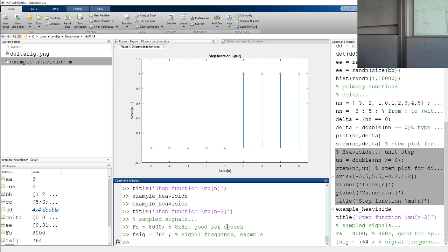So if you are using this capacitive type microphone, you basically can just use the 3 volt bias. Then this voltage should be around that one. That's one way. Otherwise, you need to do some analog electronics before that.